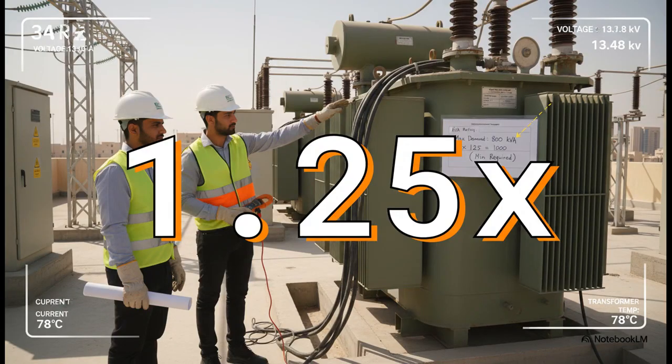So, to handle that brutal heat and make sure the system is reliable, the SEC and SBC codes give you a clear instruction. You take your calculated maximum demand and you multiply it by a safety factor of at least 1.25. That number gives you the minimum kVA for your transformer, and you better believe the inspector will check that calculation against your transformer's datasheet.